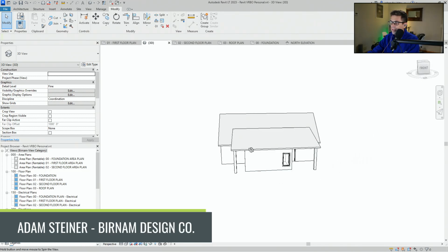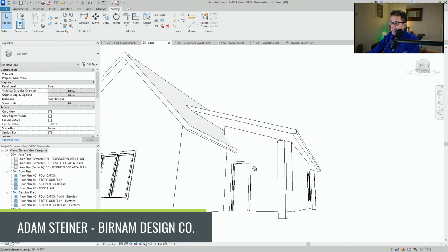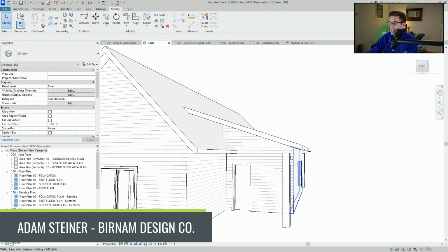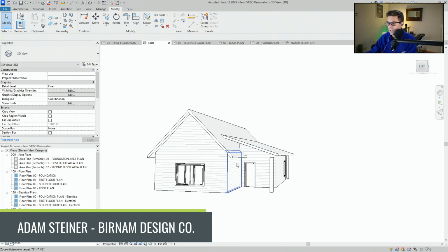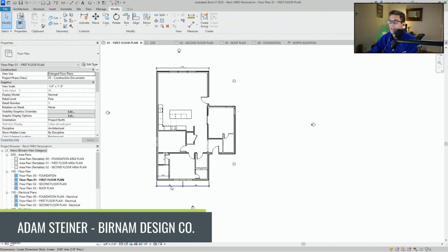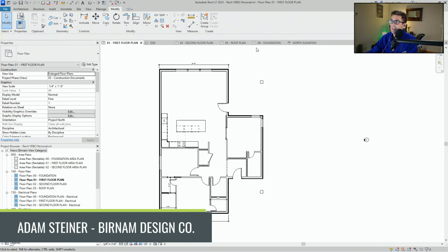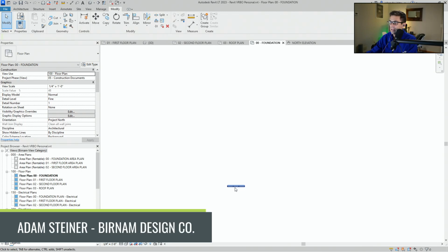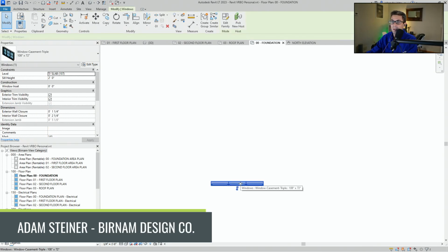Okay, although, my plan with framing is not to leave these areas vaulted. So I think I'm actually going to need a wall in here that sits on the top of that column so that I can do a flat ceiling in those porches. Just a lot easier of construction. Will save me some money if I end up building this ever. Before we do that, though, let's do our patios, our foundation, and all that. Why are you here?